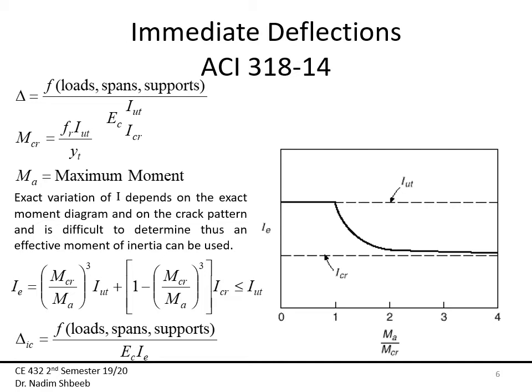So there's a difference of about 7 centimeters, and then the question becomes, is it fair to impose that 10% over the whole slab? So in that case, you probably would assume that you're going to take the minimum value, but then you have to calculate the deflection to make sure that you are within the limits. So these are the two things where I think it might arise where we actually need to calculate the deflection.